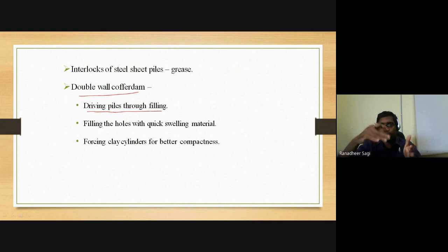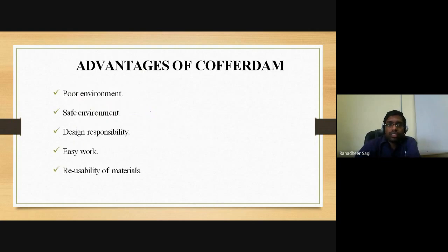The material filled inside can be one which undergoes swelling, with an increase in volume because of any moisture which comes in contact. Once the volume increases, the interconnected void paths available within that volume automatically decrease, resulting in the prevention of leakage through that cross section.